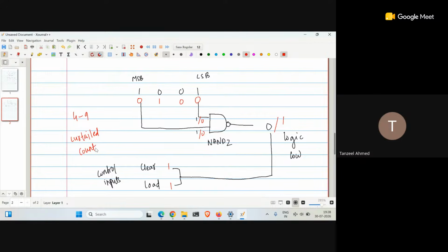By the way, this part that is delivering the control signal is called a combinational circuit, because it is providing an output based on whatever is the current input, and it is doing it immediately. And using a combinational circuit, you can prepare control signals for a sequential circuit.